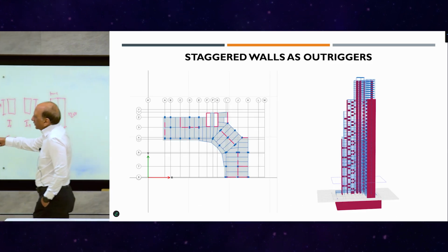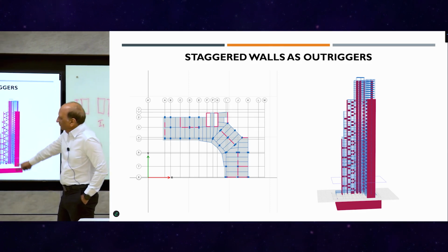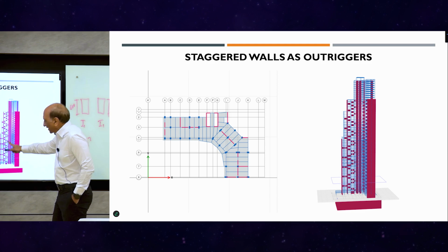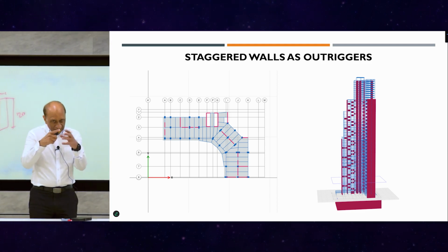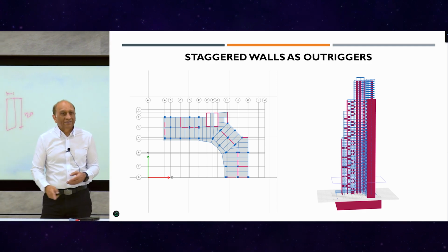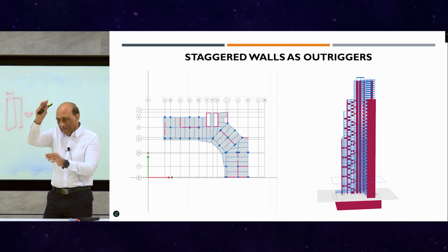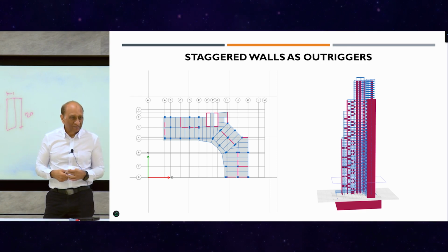This is a building, the tallest building in Philippines until recently. And this was the first building that we did. And then here you can see we used the partition walls to actually create a staggered truss system by using the flat walls, but as a truss. So it's a bracing, hidden bracing inside the building, because those walls are placed in a sequence that they also act as a truss, global truss, and also as flat walls.